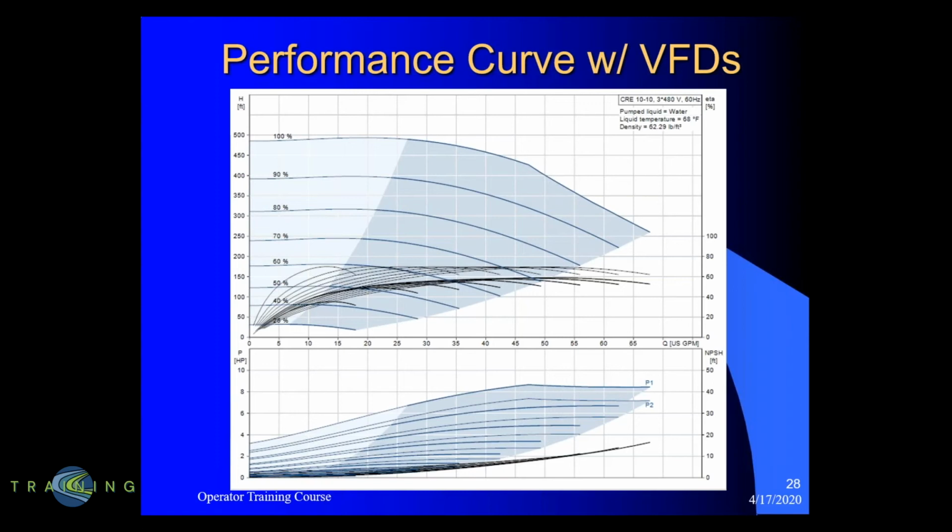So instead of the old way we always did it, having a pump pressure switch differential, which might turn on at 40 pounds and turn off at 60 pounds, so there was a differential, now we'll try to change the speed of the pump to maintain a downstream pressure in order to have a consistent pressure instead of that differential. It's a much better process.